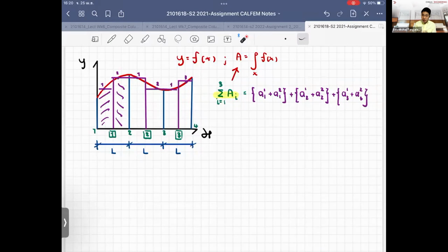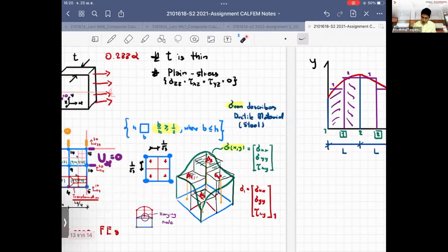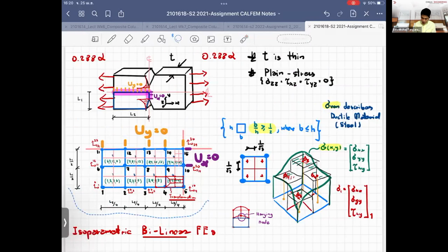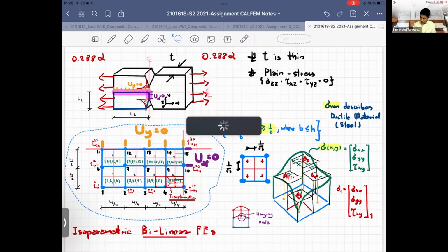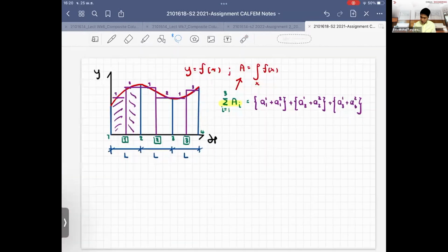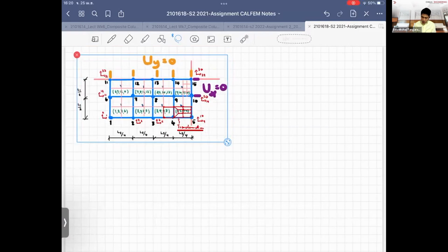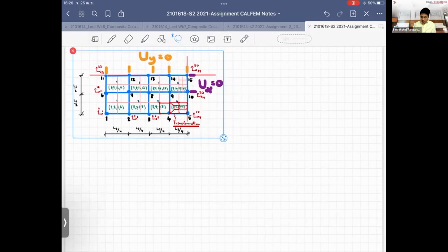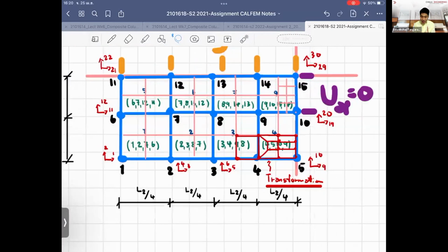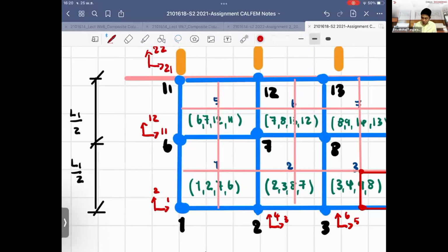Because what we do here, we try to approximate the stress value and so on. Let me capture this. Assuming that you are looking at the notch problem again, and don't forget, this is important, every time when you subdivide the element, don't forget that you have the information of the forces, and the force applied to the node will be discretized as well, the value of them.